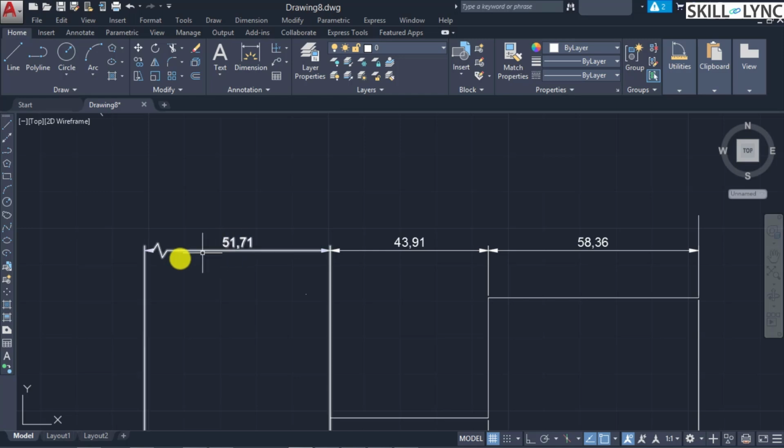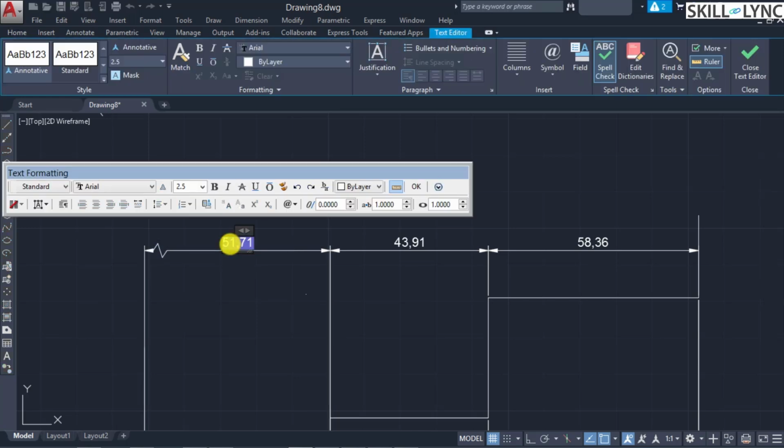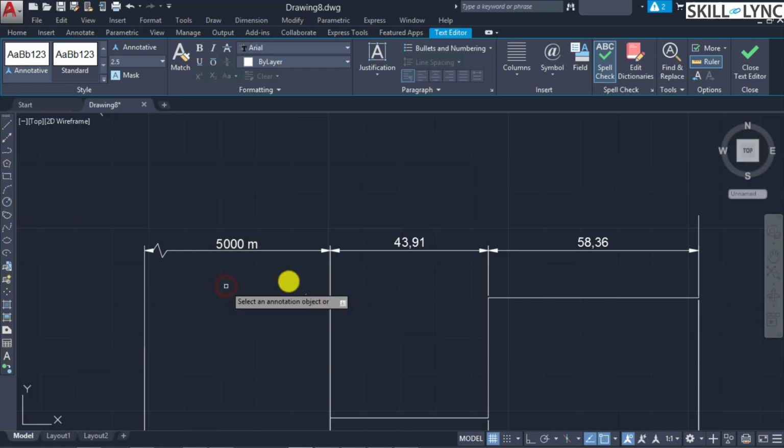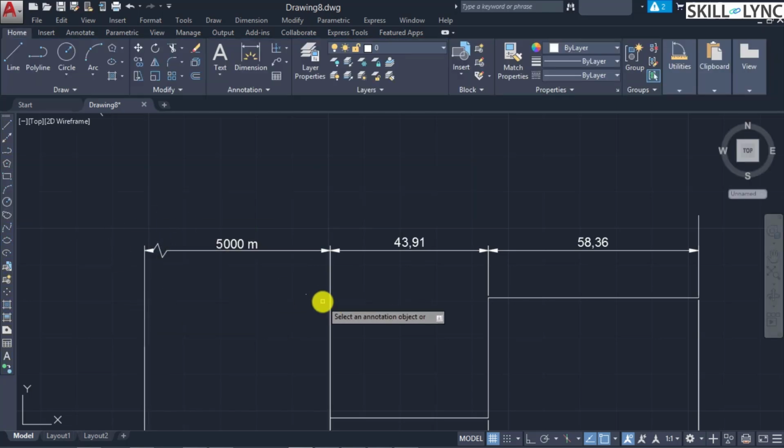So it means that on the drawing the physical distance might be only 5 centimeter, but here it denotes a longer range. Suppose it is like say 5000 meters. So this is how the true distance of this dimension length is a different value, but we are overriding that using this jog linear dimension command. So this is used for specifying an unmeasurable quantity on the physical drawing.